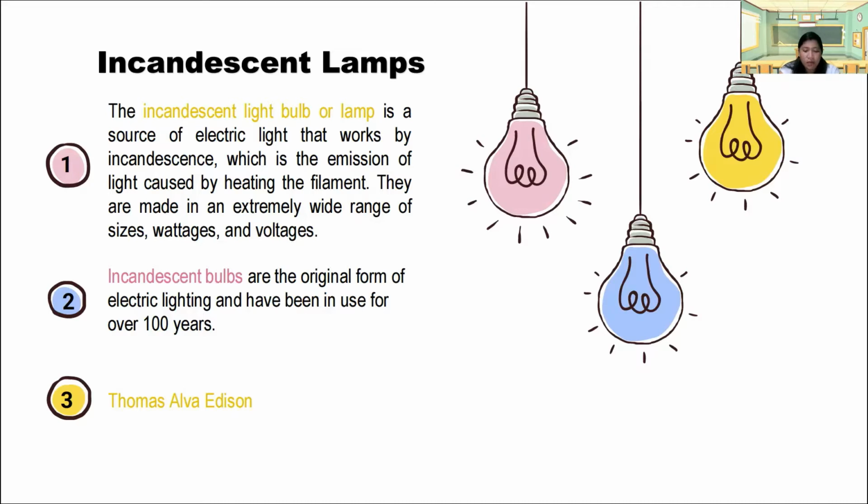An incandescent bulb typically consists of a glass enclosure containing a tungsten filament. An electric current passes through the filament, heating it to a temperature that produces light. Incandescent light bulbs usually contain a stem or a glass mount attached to the bulb base, which allows the electric contacts to run through the envelope without gas or air leaks. Small wires embedded in the stem support the filament and/or its lead wires.